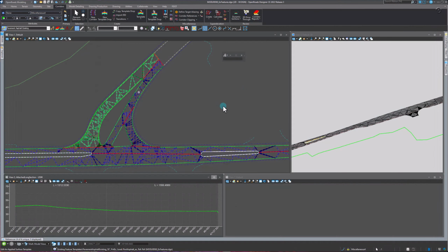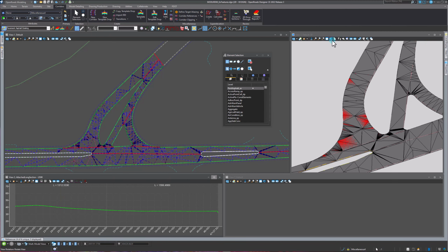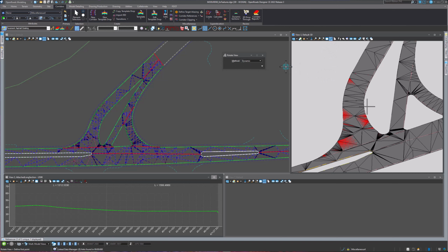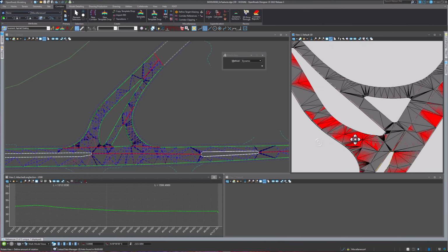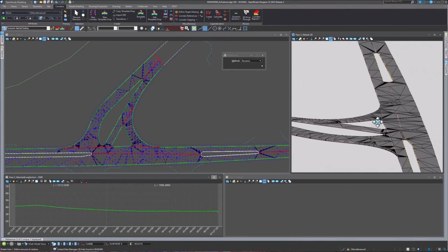Then if I hit OK, that will change that one. So if we come over here in our 3D view and make sure your 3D view is active. This works a little different when you're in 3D. I have dynamic turned on, which is what I usually do in 3D. The best thing you can do is grab this little crosshair and snap it to a point. That's now the point that you're rotating the view around, which makes it a lot easier to manipulate.